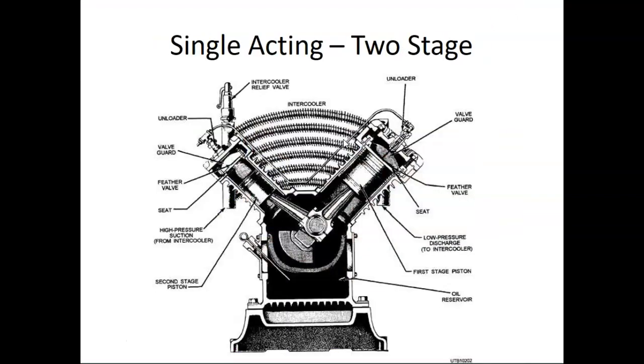All right, so this is a single acting two stage. Okay. And this one actually has an intercooler. So what would we say the intercooler was for? Cool it down between stages, because the last thing you want is a lot of heat built up in your system. Right?